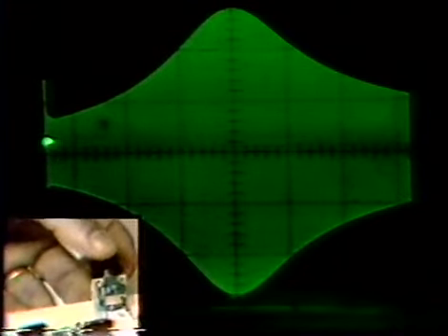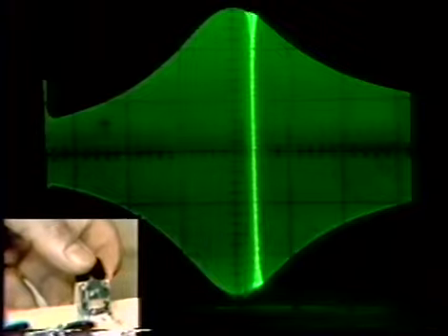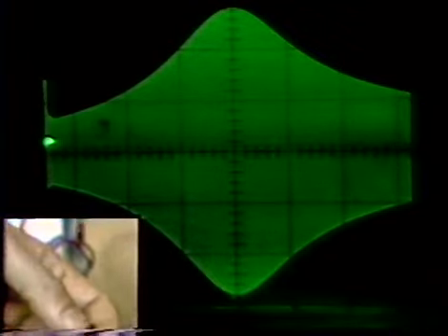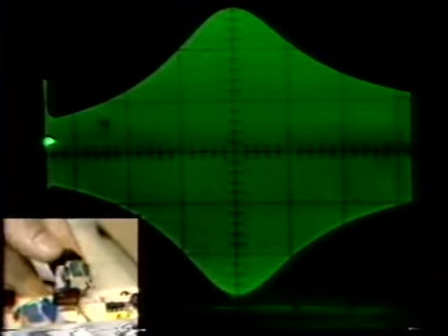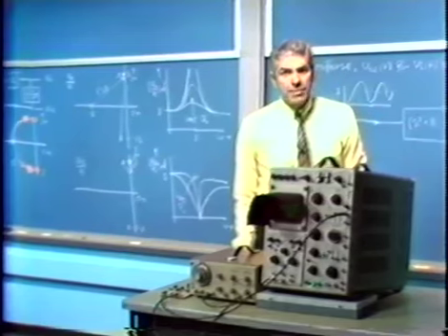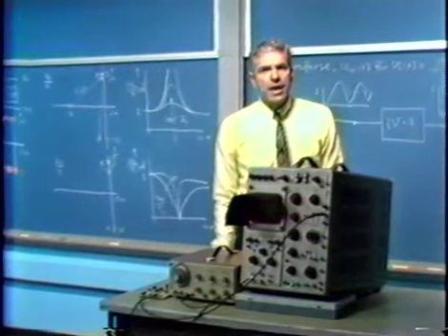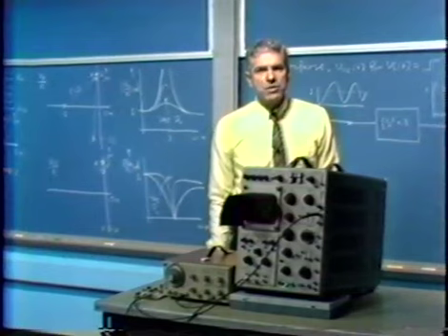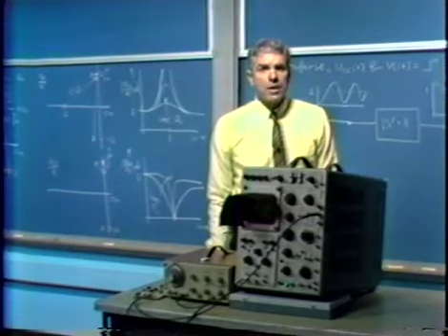And finally, the maximum value of A0 that we can get with our system. Here we have a range of A0s that only allows us to get down to possibly a damping ratio of 0.1 or so for the dominant pole pair. So we don't get a very highly resonant effect, but we certainly get a very observable one. So that's the response of the system when we're looking at the one output.